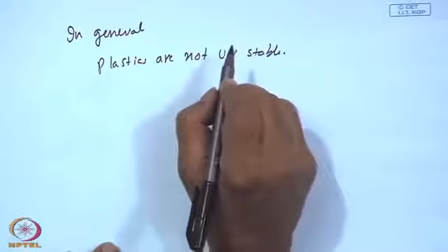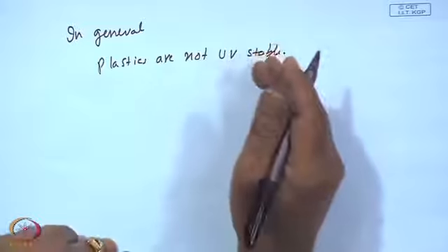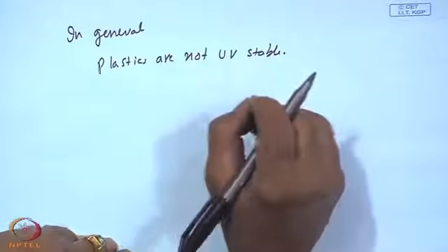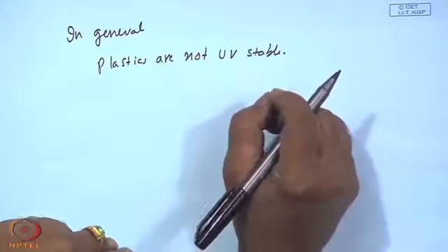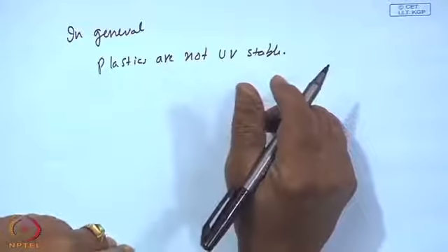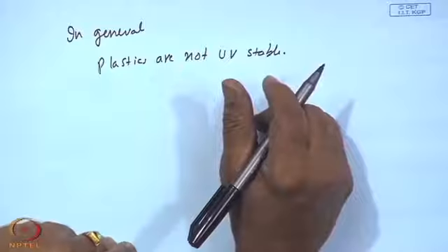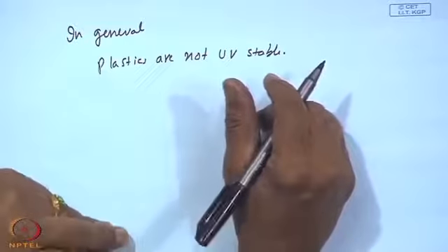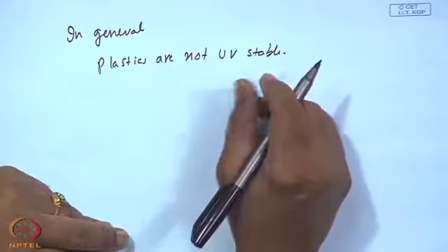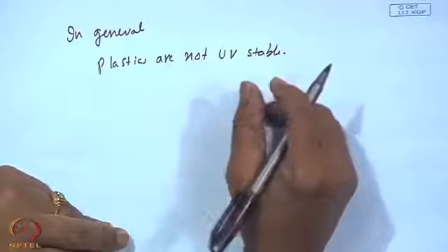The ultraviolet radiation, though 2% or 4%, will make the plastics unstable, and after a while they lose their color, they lose their rigidity, they simply break. In fact, our common experience shows one fine morning when you are picking up a bucket of water, that bucket breaks down after 4 or 5 years of service, and you can't fathom the reason why it happens.